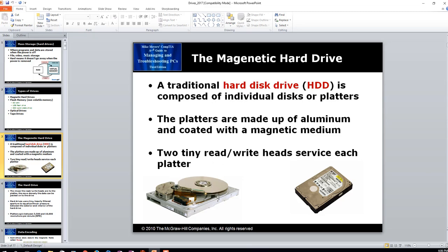This is a drive that has two platters. There are actually four heads there, one for each side. I know there's not much room there, but it'll fit in between there. There's actually a top and the bottom of this one, and the top of that one, that will fit in there. Those heads go back and forth across that platter, reading ones and zeros, or reading the magnetic fields. Now this is the inside of the drive. Normally all this is sealed inside a metal case. So once they manufacture it, this is sealed off, and you would never open it for normal servicing.